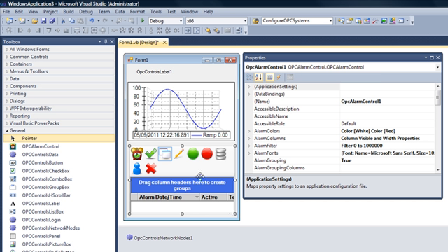If the web application is running on the same computer as the OPC system service, the HMI, the trend, and alarm controls would all just use localhost in the connections, and then the client browsers would of course connect to that web application. So there would be no point in defining a remote network node when you're working with web controls when the web application is going to run on the same computer as the OPC system service. But for the Windows applications, you do want to include that remote node as we're doing here.